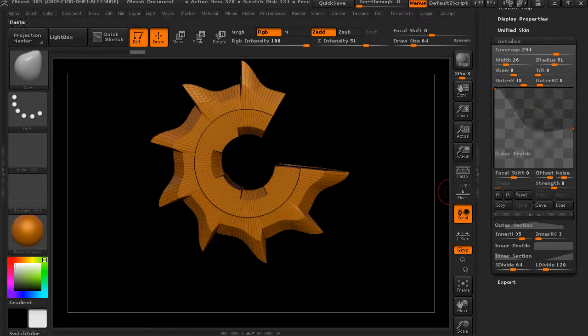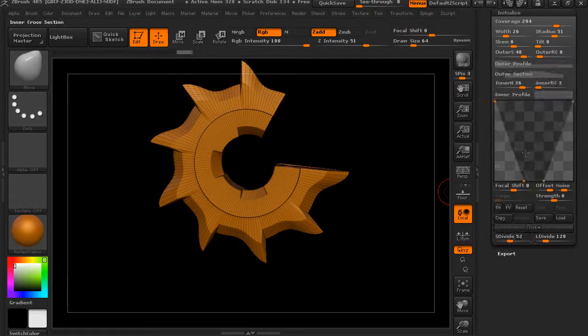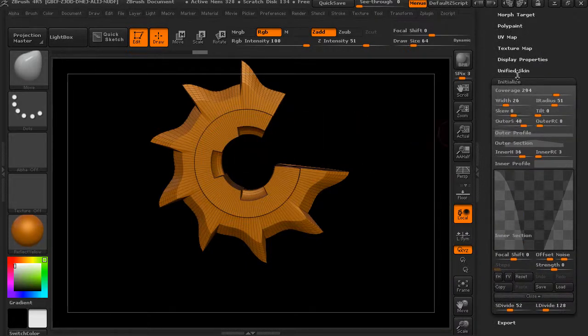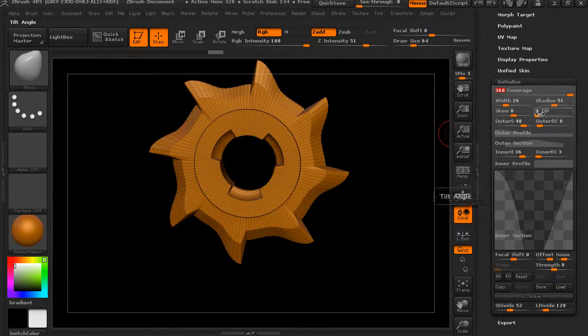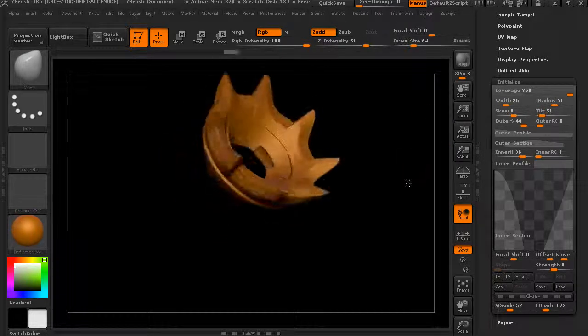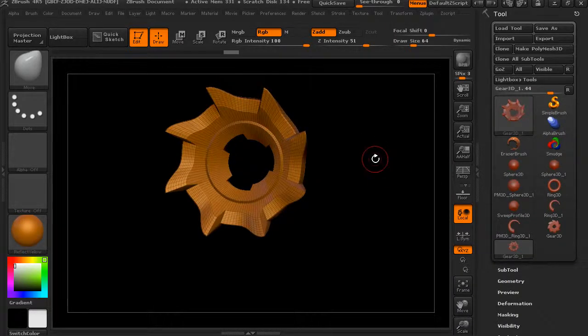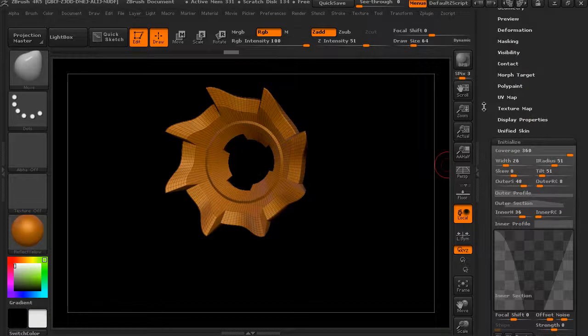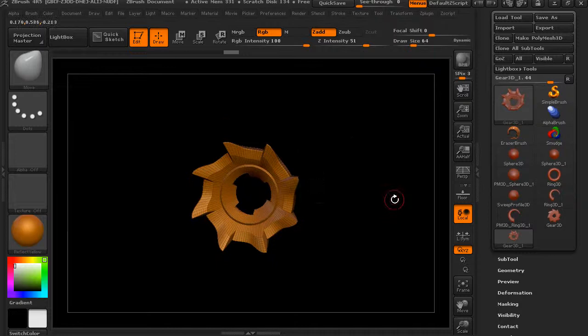You see this sort of interface a lot. You can add those little intersections, those divisions here. You can change that look. So this particular one has a ton of initialize settings that you can change to get something that looks right, if you're creating a gear or some sort of mechanical detail. You can go in here and really modify a lot of this before you even get into trying to sculpt it. So, the more you can do with your initialize settings to get that starting point, the better off you are when you get going with building the rest of your model.